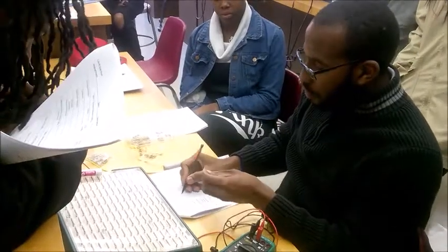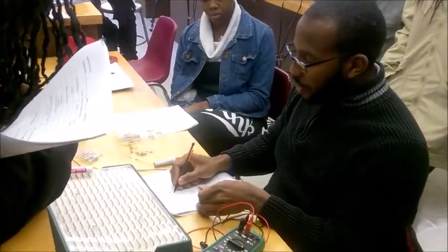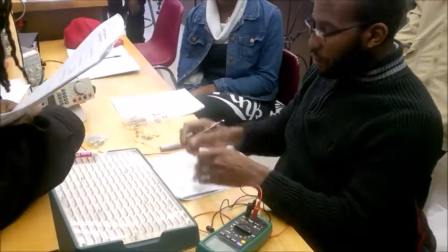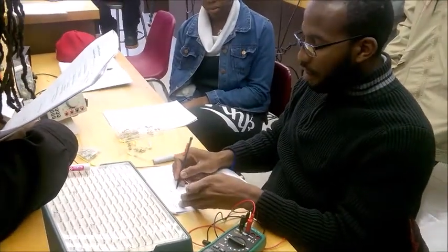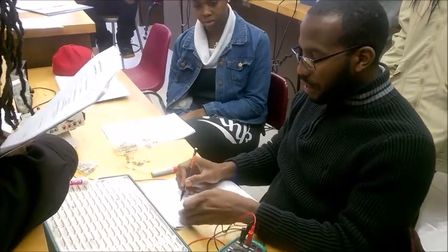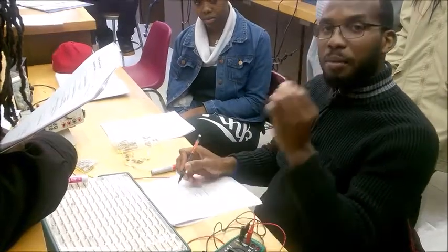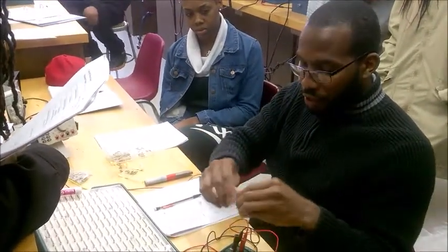So again, first thing I will do, calculate what this is using the color code. Put my 100 ohms here. The tolerance is gold, so this is plus or minus 5%. The maximum resistance is going to be 105. We already calculated this one. The minimum is going to be 95 ohms. All the units here. The measured resistance, this is where I need to measure the resistance.